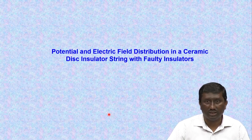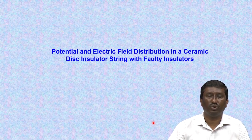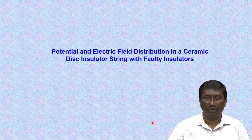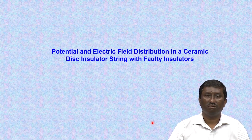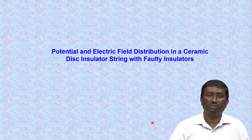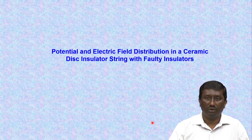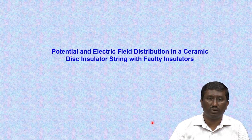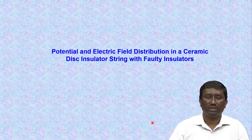So, we were discussing with the type test what happens to the field and electric potential, how it gets modified, how it gets distributed, particularly in a ceramic disc insulator string if the string contains faulty insulators. Again, the faulty insulators could be at any position in the string. This could happen because of the failure of insulators due to tension loads or because of an inherent property of the insulator which could have failed over a period of time, losing its insulating properties. So, the position where the failure has happened is very important.